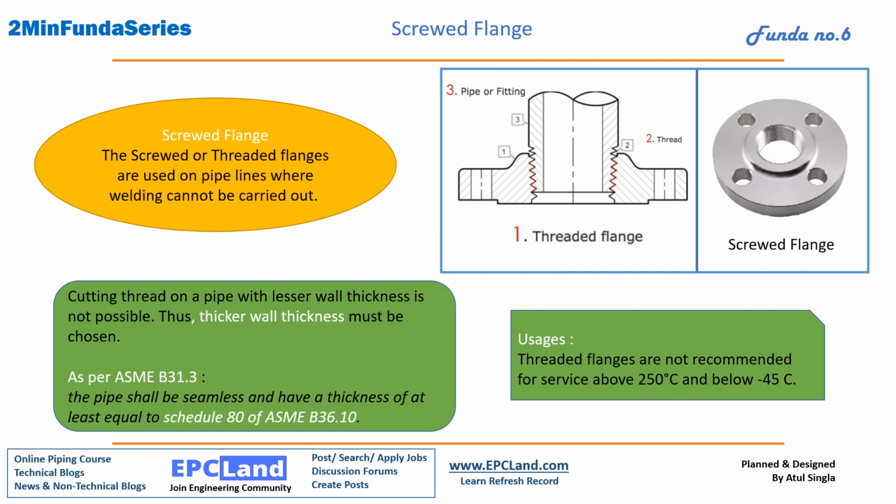Screwed flanges. Screwed flanges or threaded flanges are used for pipelines where welding cannot be carried out. So this is the basic intention to use these flanges. Now, for cutting the threads on pipes, we require a thicker wall thickness, so this cannot be used on pipes where the thickness is less. As per B31.3, wherever we are going to use screwed flanges, the wall thickness should be at least schedule 80. For the dimensional standard we need to refer to B36.10, and for schedule 80 or above we can go for threaded flanges.